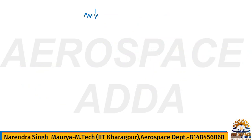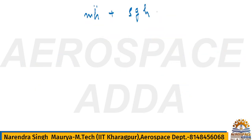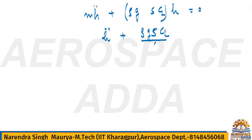Now you can write m h double dot plus rho g S C_L into h, taking h outside, is equal to 0. Now if you compare with the natural frequency form, you can write h double dot plus rho g S C_L by m, the mass, into h is equal to 0.